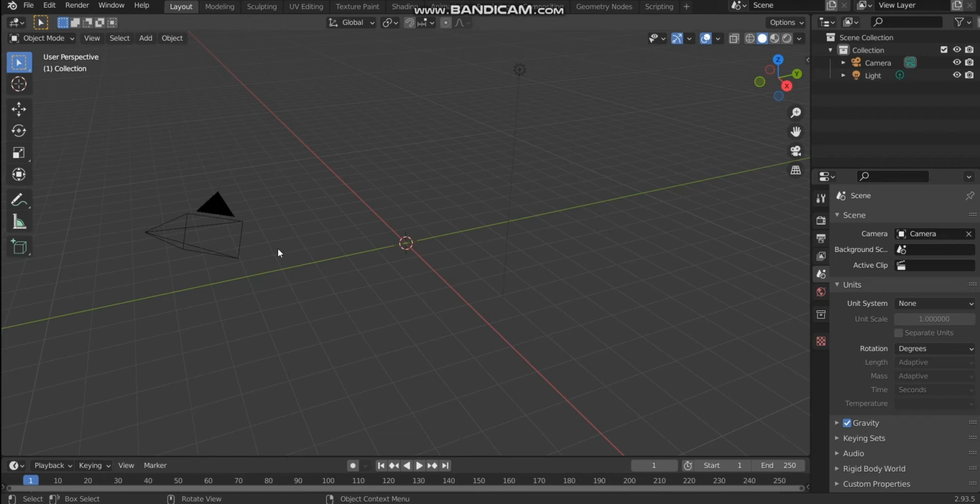So our base is technically a hollow cylinder with a certain thickness. In order to create a hollow cylinder, we'll be creating two concentric cylinders and then subtract the smaller one from the bigger one. So let's create the first cylinder.